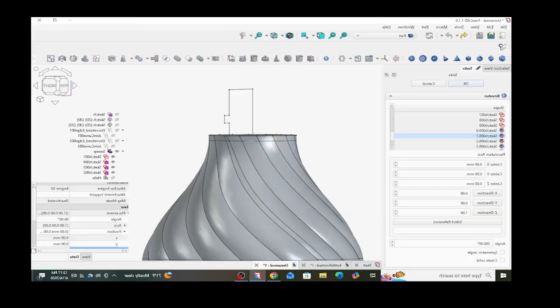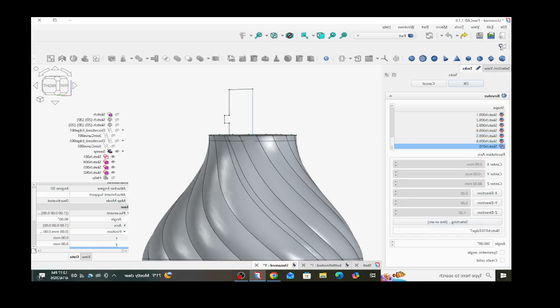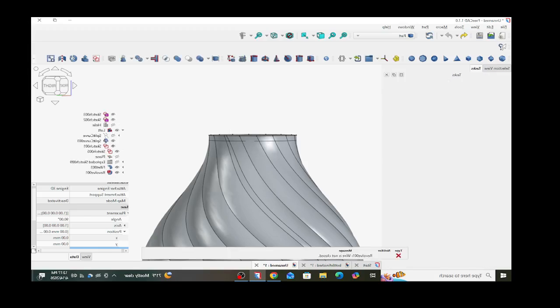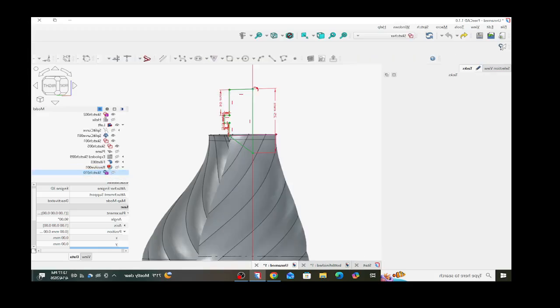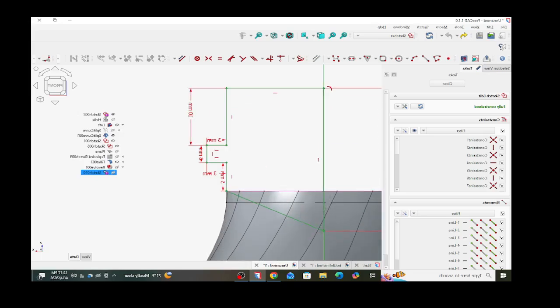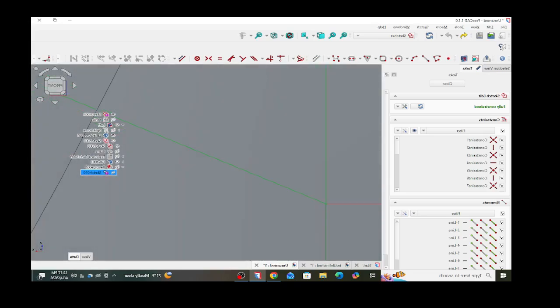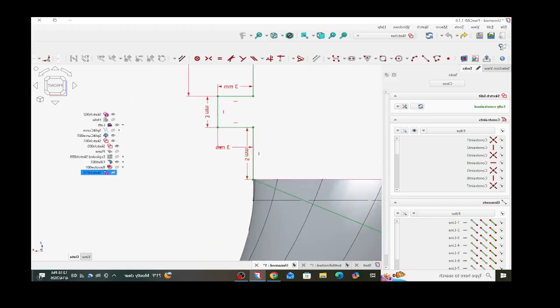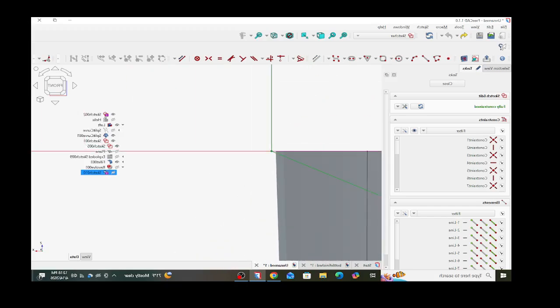I'm going to revolve that new sketch, sketch 10. Select a reference line, the center line. And we want to create a solid. Alright, we got a wire not closed error. I have to go back into that sketch. Even though it's fully constrained, sometimes you get these. There's a way to highlight those.